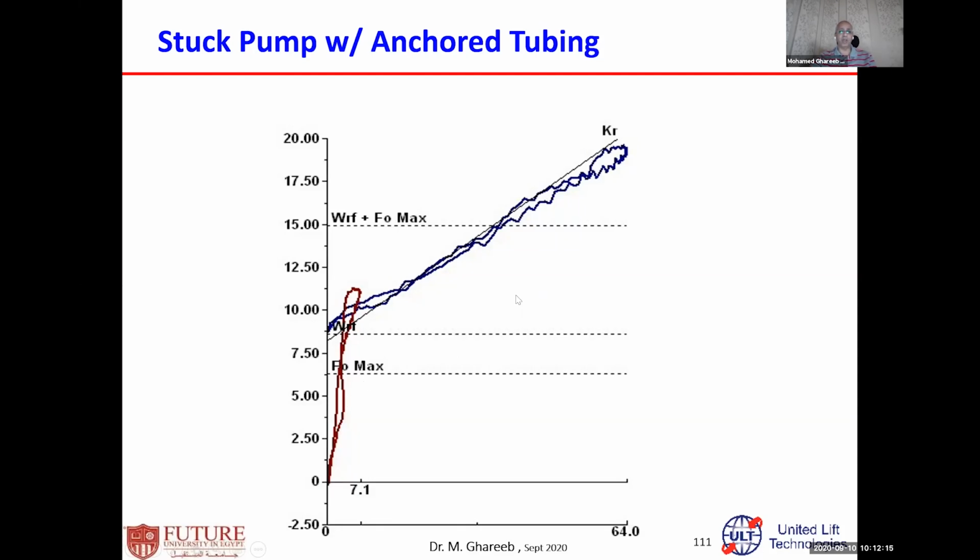It's from one well. When we found this one and started analyzing, we found the pump is stuck, and the rod has enough elasticity to stretch, because the stroke length is not big, it's a short stroke length. Then the pump starts to go up, stretches the rod up to a certain point, which is not reaching the rod's breaking point, and then starts to go down. This is usually for short stroke length, high elasticity rods, and so on. You can find some like this.